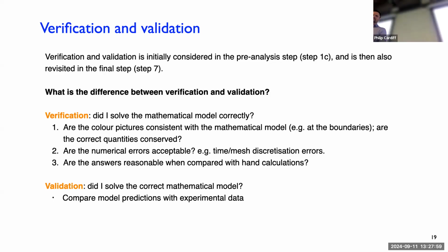So sometimes you'll see in literature that people won't do a mesh study, they won't do any verification. They just set up a model, directly compare to experiment, and they say, it gives the same. This is a validated model. But it just could be by luck. Their mesh error was huge, but they made another assumption which canceled that out. So just by coincidence, they matched it. Or people will just change a few things in the inputs until they get it to match the experiment. And they're like, it's a validated model, this is great. So that's easier to do, but it is not a model that will generalize. It's not a model that will have great predictive power.